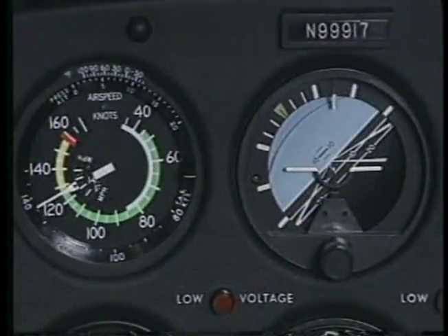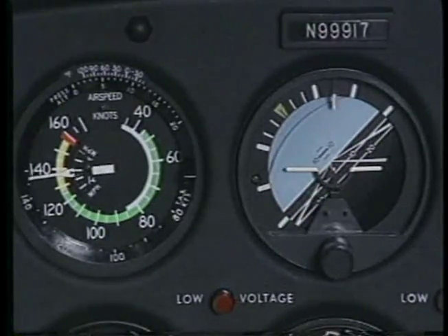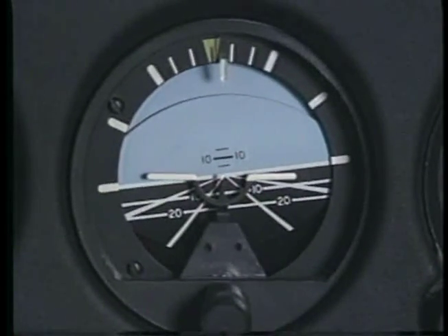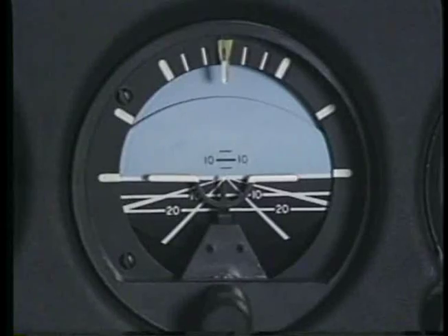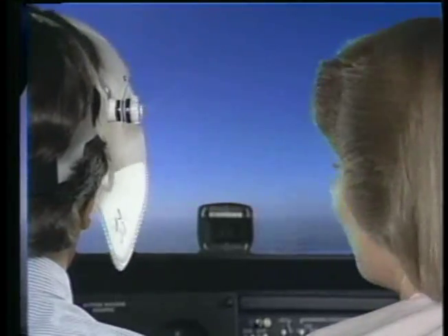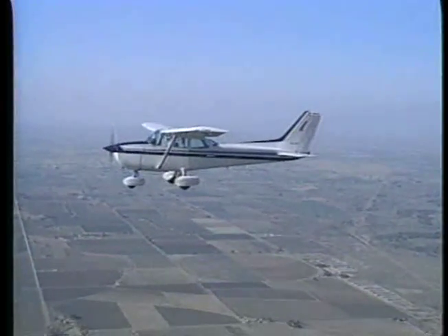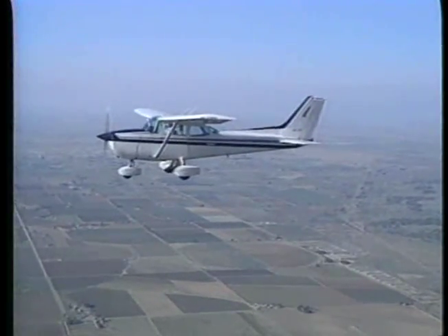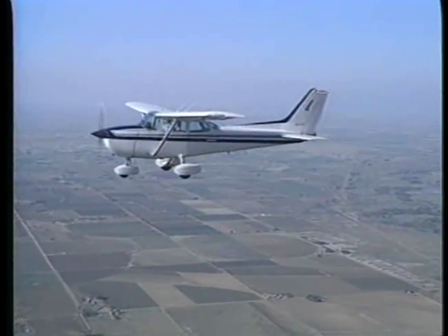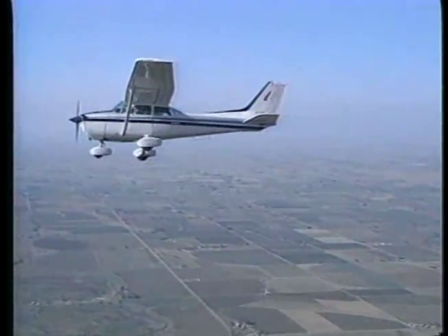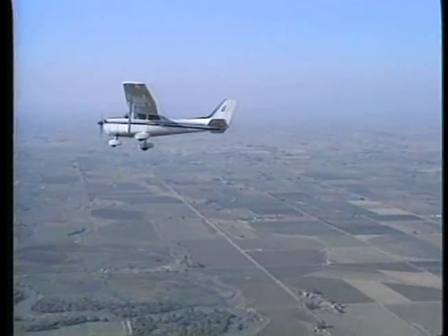Conversely, if the pitch attitude is low and the airspeed increasing, you'll need to reduce power to prevent excessive airspeed, adjust the wings to level, and then raise the pitch to a straight and level flight attitude. Your initial training in attitude instrument flying does not qualify you to fly in IFR conditions without an instrument rating. However, it does provide you with basic emergency skills if you inadvertently lose outside visual references. It also helps you interpret the instruments more effectively during VFR conditions.